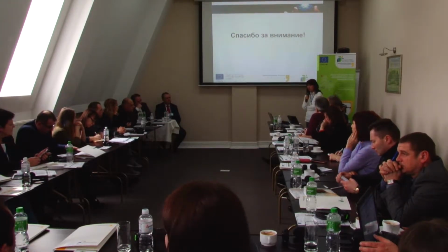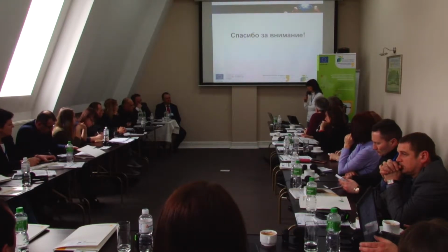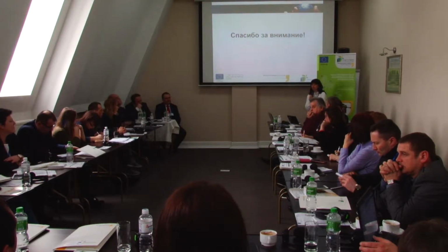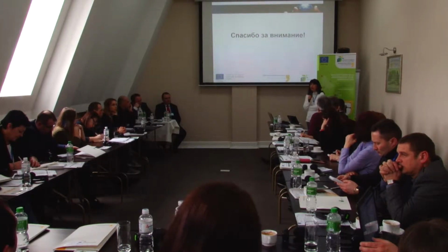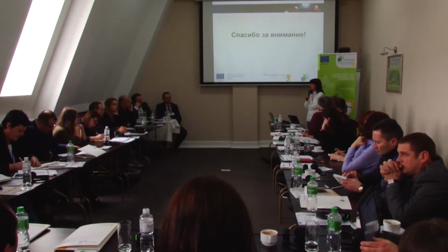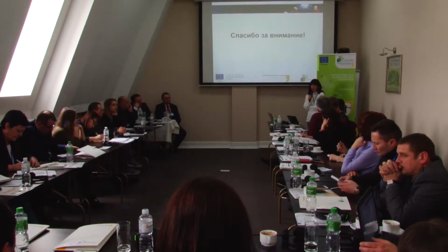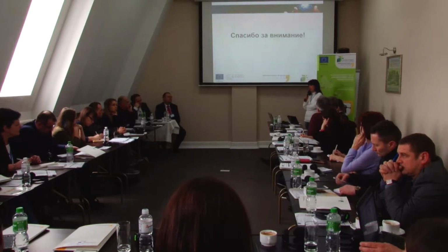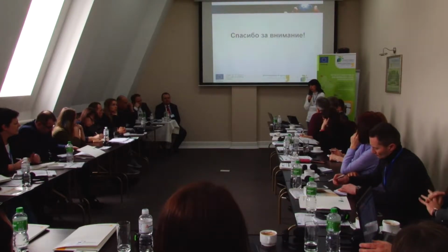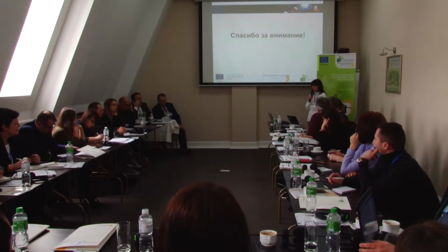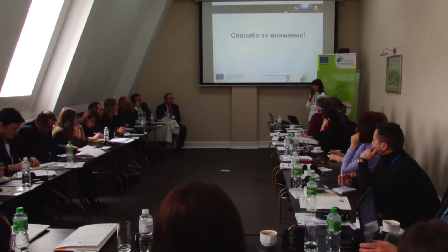Then, after you develop the terms of reference, you need to get permission from the executive committee for the development of technical design documents and start choosing the contractor which will perform the design works. Design works in Ukraine can be done without any open tendering if the amount is under 1.5 million hryvnias. So it is within your mandate to choose the contractor which will do the designing works, and you don't necessarily have to use the electronic Prozorro system.